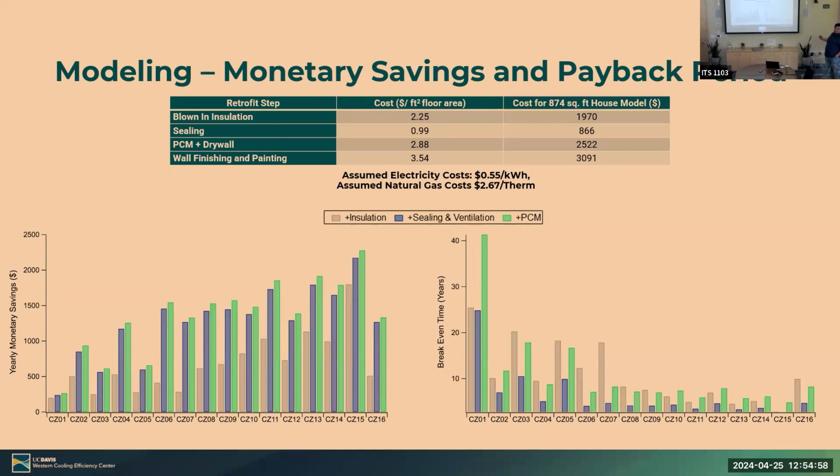So what's the payback of insulating an uninsulated wall? The payback period on an insulated wall is roughly 8 years. I don't have the number right off the top of my head, so, approximately 8 years. That's drilling the holes and blowing the insulation. What's happening in the attic in this model? Is there insulation in the attic? This is just adding wall insulation, with assumed attic insulation. Okay, with the attic already insulated.